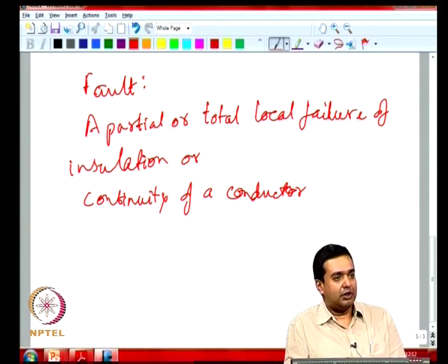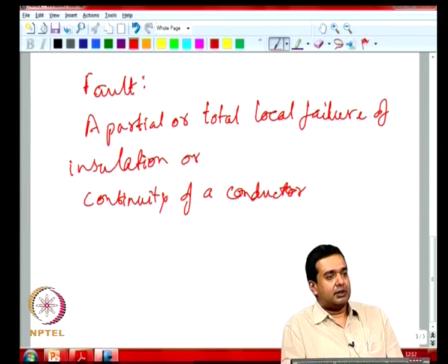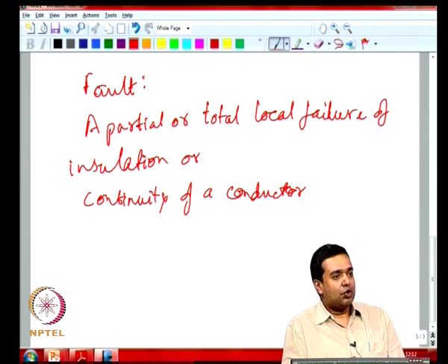If it is an exposed line, you would have insulators on the electric poles and they might arc over. So, often the over voltage caused by lightning is then followed by arcing or essentially short circuit,